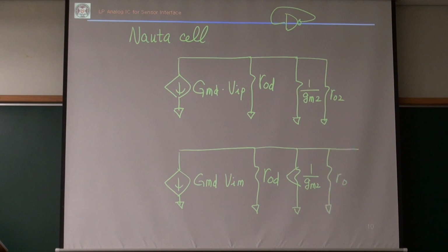And then between those two, we have some resistance. What is that? Minus 2 over gm, negative resistance, right? I think it's a parallel. This is gm3, the cross-coupled inverter, and this one is 2 ro3, something like that.